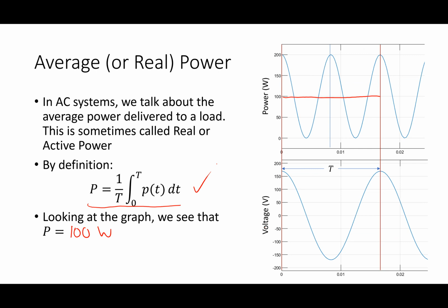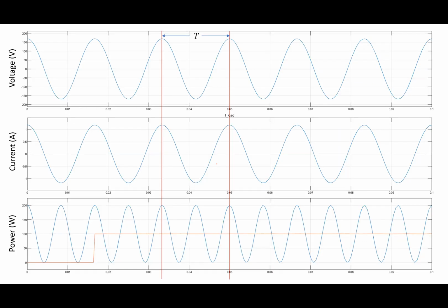But we're basically going to use the results of this calculus. We're going to say that number 100 watts is the average power, because it's tricky to define one number when it comes to the power of an AC load. The power, if it's V times I, is this kind of cosine going up and down, and it actually has twice the frequency of either the voltage or the current. So it's very confusing.